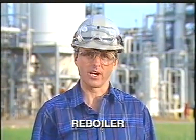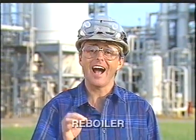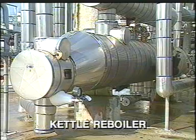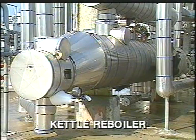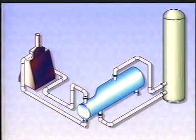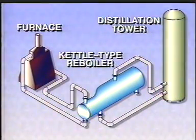Another application for heat exchangers is as a reboiler. Reboilers are used in systems that heat and vaporize hydrocarbons. This one is a kettle-type reboiler. It is simply a shell and tube exchanger surrounded by an enlarged shell that accommodates vapor. Let's examine the system. This system includes a distillation tower, a furnace, and a kettle-type reboiler.